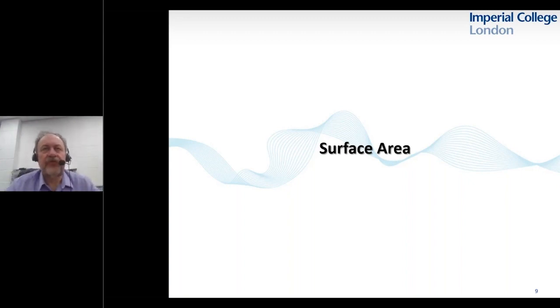Also, if I've got a material that interacts with water vapor, that is also a complication, because the techniques that are typically used to measure surface area require the sample to be fully dried. And in some cases that could destroy the material. Let's imagine you've got a dihydrate, it's a powder, you want to measure the surface area, but as soon as you put it under vacuum, you dehydrate it and you lose the structure. Now the surface area you've measured is totally irrelevant. So it turns out with IGC we can do two particular sorts of surface area experiments. We can do low surface areas and we can also do surface areas at different humidities. And we'll show briefly an example of those.